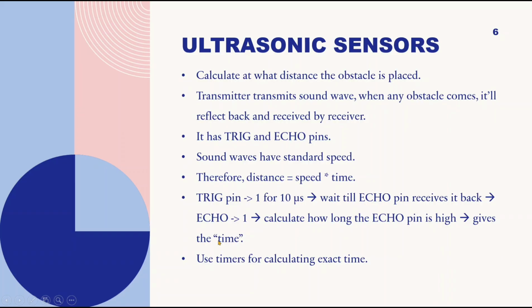And we can calculate the time by measuring how long the echo pin was high. This time is used for calculating the distance, how far our obstacle is. We use this formula, distance is equal to speed into time, and we use timers for calculating the exact time.